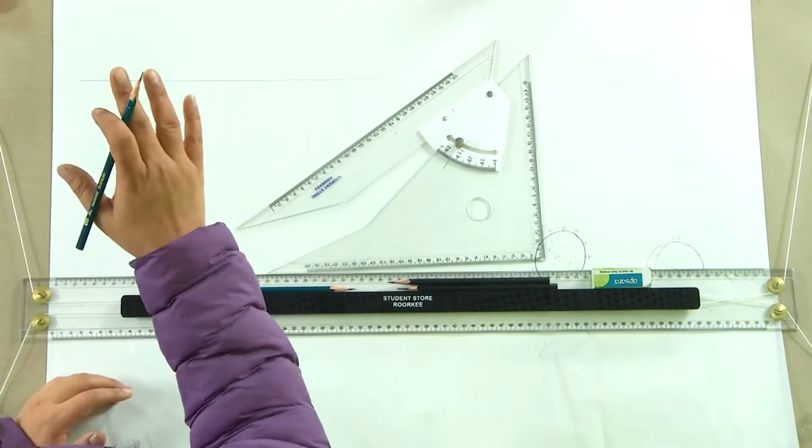What we see in this case, when we see it from the top, is the true shape because the base is being kept parallel to the HP. So, in such a case, when the axis is perpendicular to the HP, we will see the true shape of the base in the HP. So, we have this.